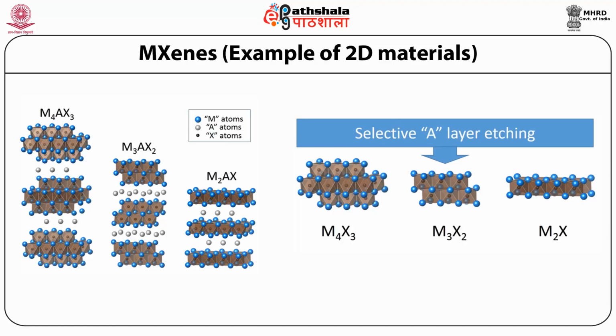First described in 2011, MXenes combine the metallic conductivity of transition metal carbides with a hydrophilic nature because of their hydroxyl or oxygen terminated surfaces. As-synthesized MXenes prepared via HF etching have an accordion-like morphology,